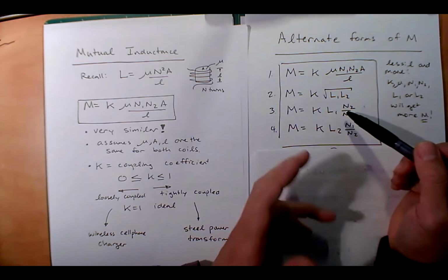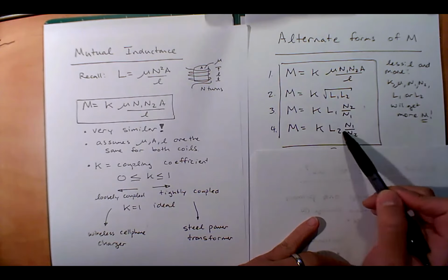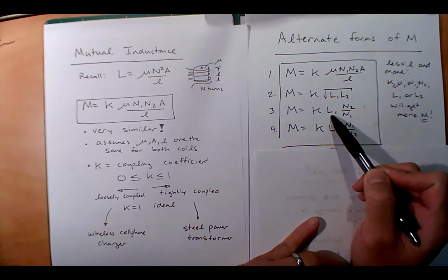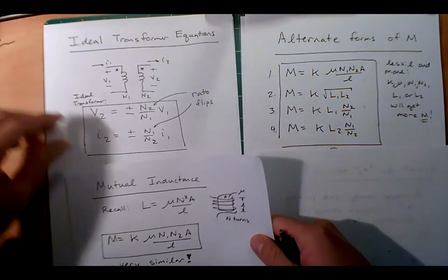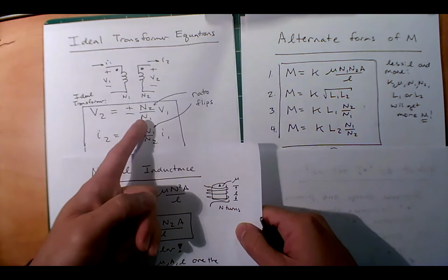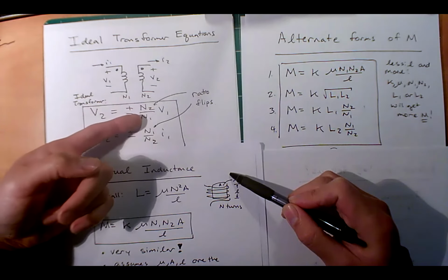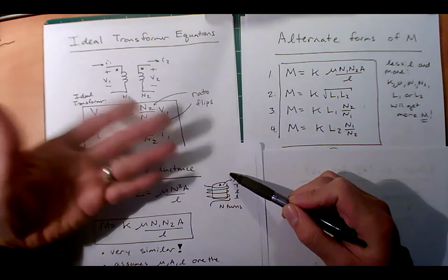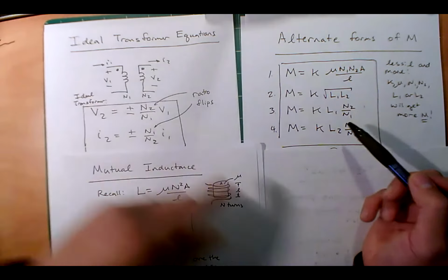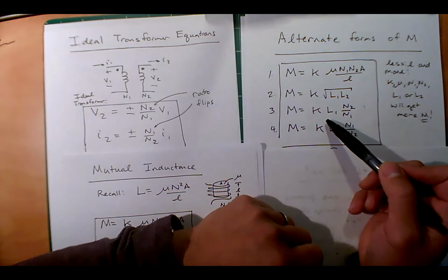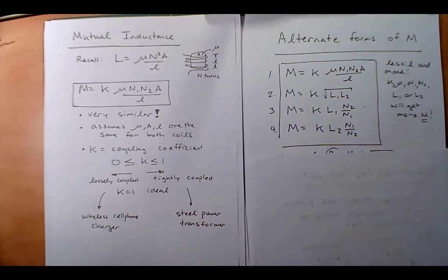Okay, and so if you're looking at the big power transformers, you can't really readily see it here, but you can maybe see it in these different forms that I might need a big inductance. Notice how this inductance doesn't necessarily show up in the ideal transformer relationships. This wouldn't tell you, if I have, let's say, a 10-to-1 ratio, and I have 100 turns to 10 turns or 10 turns to 1 turn, what the difference is, because all these terms don't pop up. We'll see later that it actually does matter, and your transformer won't behave as well if I have too small an inductance. Okay, interesting. Let's keep going.